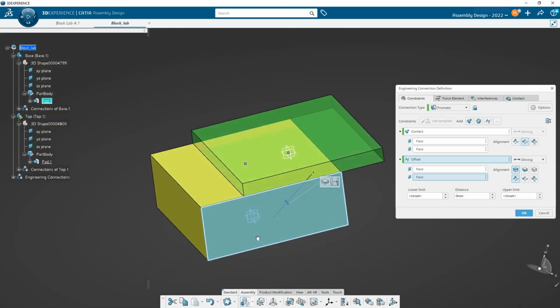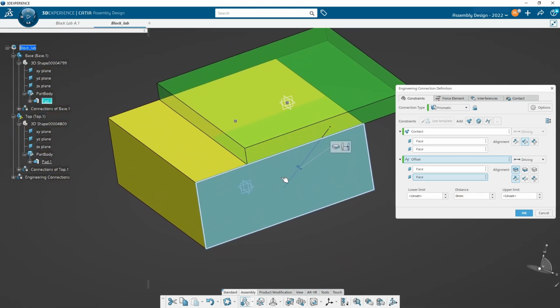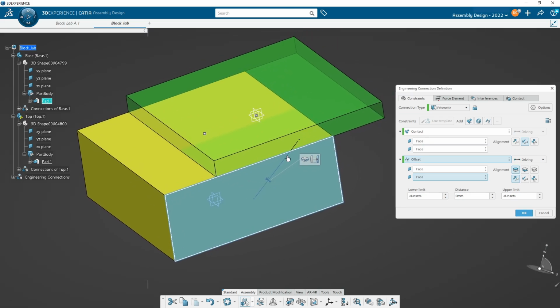So we're getting it sorted out, but you see how it takes a few of these constraint operations to get this stuck where it's supposed to be. So where else could it move? Obviously, it could move side to side. It can't necessarily move up and down. We can't make it twist any longer because we're stuck to that face.